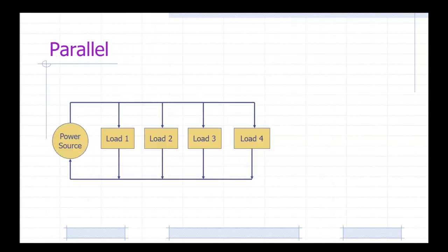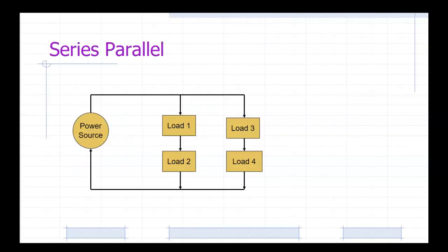Versus parallel, in which you have a singular source and each load goes back to that source. That's why each one of these lights runs on 120. Does that make sense? Okay. So technically your whole house is wired parallel. We'll go into something else on that later.